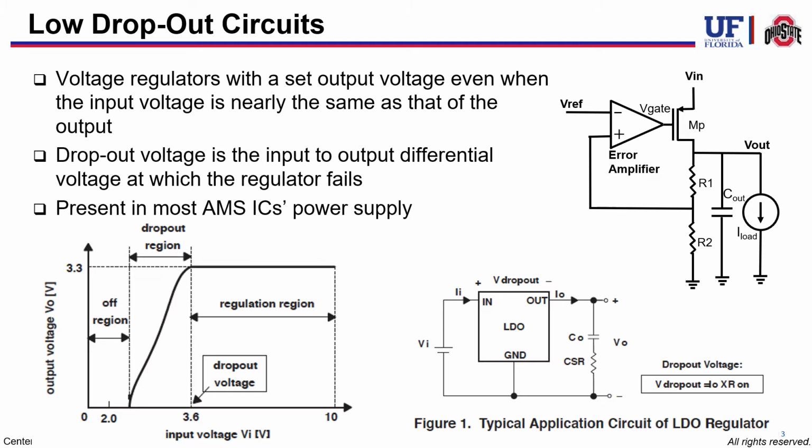One of the methods to determine whether an AMS primitive is counterfeit or recycled is by understanding and analyzing LDO circuits, given that these circuits are an essential component in most power supplies of analog mixed signal chips nowadays. In simple words, an LDO is a linear voltage regulator that has the ability to have a very low voltage drop across it. The two main functions of an LDO are to regulate the input supply voltage to the voltage required by the load and to supply a very low noise output voltage.